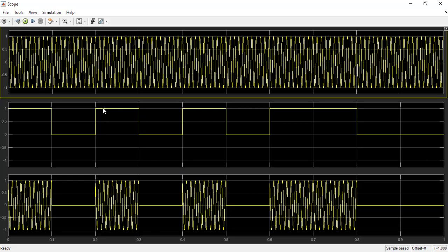So this signal is our digital sequence, and we are modulating it with a cos carrier of 100 Hz frequency, and then the whole thing turns to an on-off keying signal like this, and that is transmitted via any method to a larger distance. Okay, so that's basically our modulation. Now we will do the demodulation part.